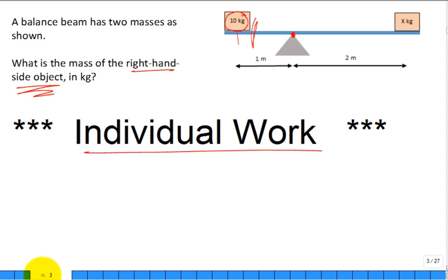If you go back to here, what was that moment arm? 2 meters. Because the weight is acting down. That's our force, our weight. And then over here, weight's acting down. What's that moment arm? 1 meter for this side. This side makes it want to rotate counterclockwise. This one clockwise. When they're balanced, the sum of those has 0 moment from that 2-force system on our balance beam.